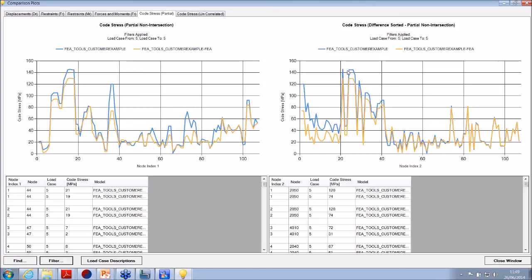And from what we've seen, and maybe Tony can confirm or deny this, most of the time this is what you're going to see. The correct SIFs and Ks are helping you and do tend to work in your favor, but like we've discussed already, this is not always the case. Don't forget that some of the SIFs can be non-conservative. If we put SIFs and flexibilities which are conservative in the model, then it might end up increasing the stresses.